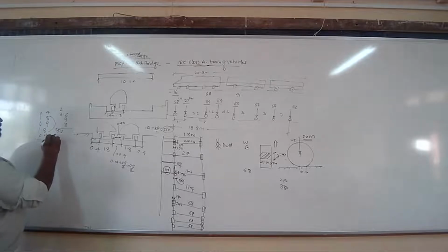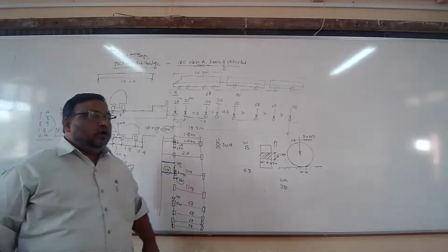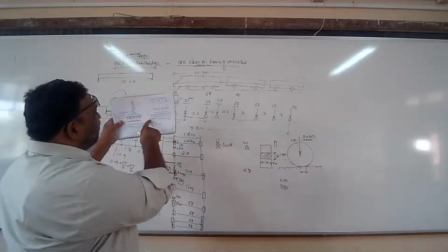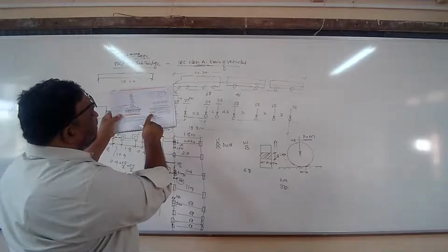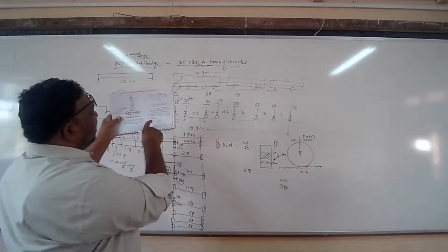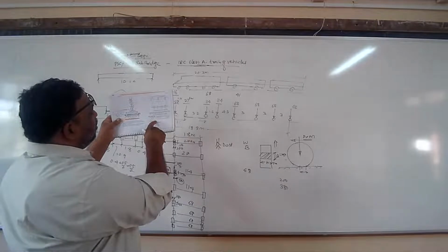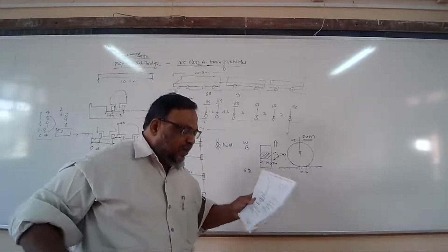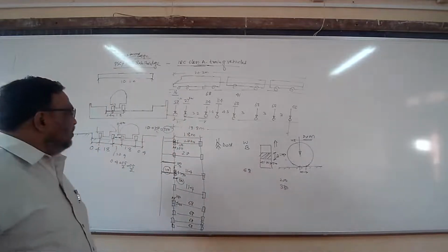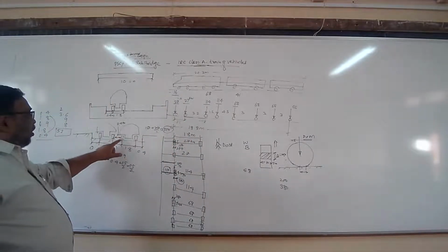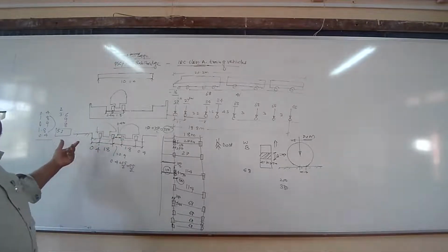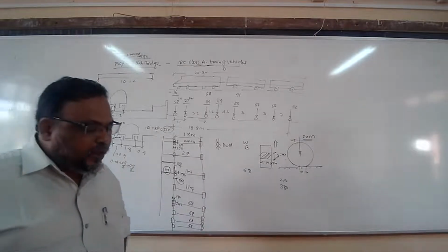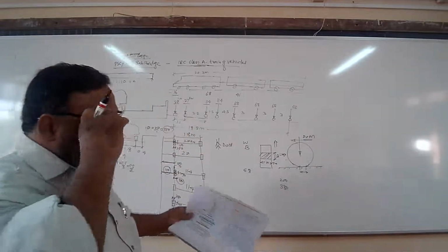So that is what is mentioned in the code. For a two-lane bridge or road, the minimum clear carriageway width must be 5.3 meters, and that is explained here how that comes to 5.3 meters. Is it okay? Are you referring table 3, page number 13? Minimum distance from the outer of the wheel is 0.4. So the minimum carriageway width must be equal to 5.3 meters. Is that okay?